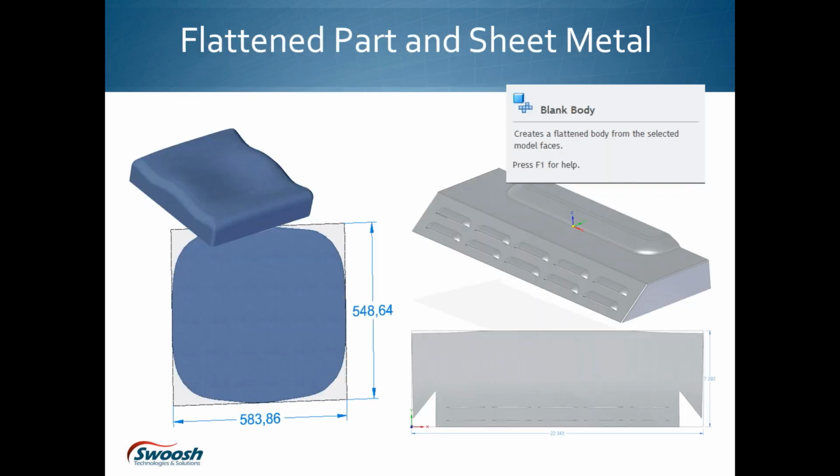What's also nice is the sheet metal. We can always flatten sheet metal parts, but we'll always have problems with deformation features. So new to ST7, we adopted this from NX: the flatten algorithm that lets you flatten pretty much any surface you want. On the left, I have a part that will be flattened to give you the blank size. We have customers who use it for generating foam or sheet sizes for pipe insulation, etc. So you can get that template really quick and know how much surface area you're going to need.